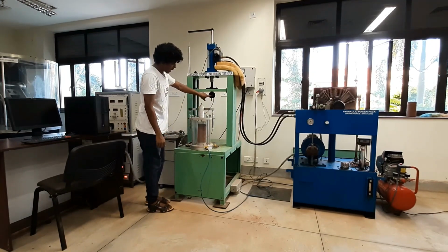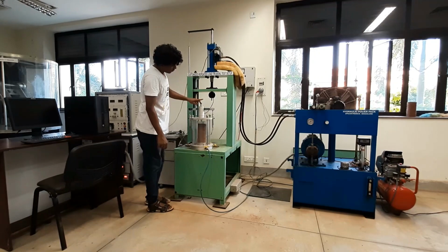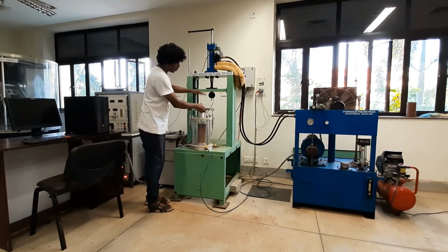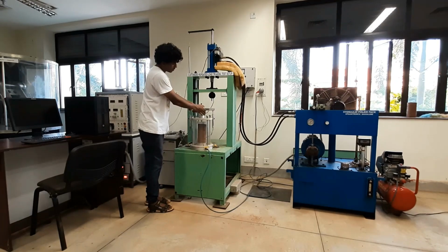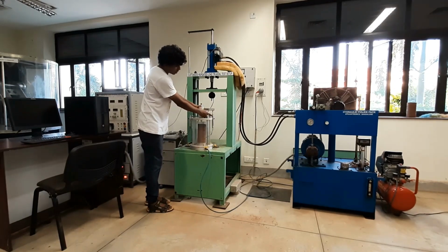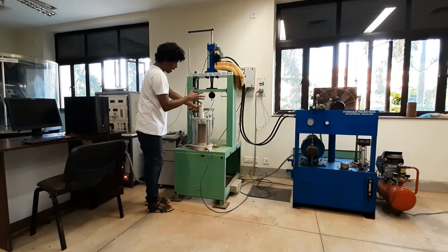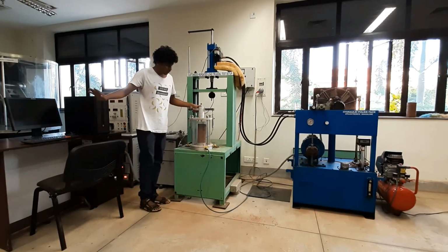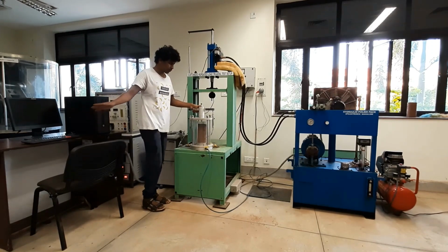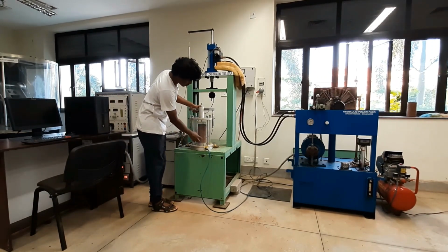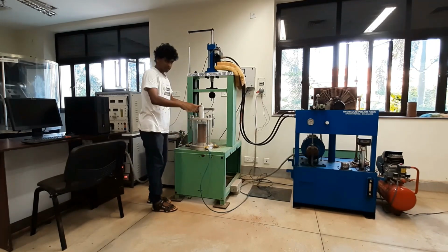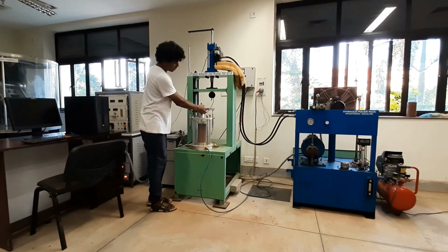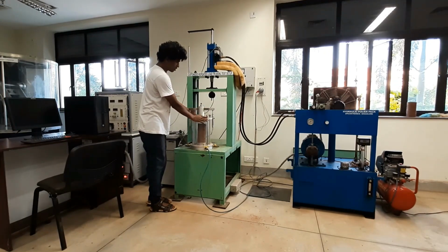Through this hammer, the loading cell will apply the cyclic loading, and accordingly this will vibrate, and the LVDT will note how much it is deforming. Afterwards we can get the delta L readings through the software, and we know the L also, so delta L by L we can get the resilient strain. That I will explain after the video. The calculations I will explain. So this is the triaxial chamber.